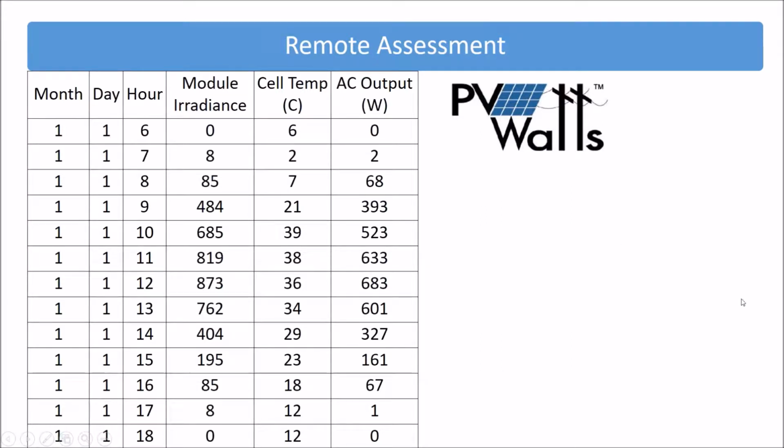And what you can see in this graph is, for every hour of the day, for every day of the year, what the power output of your solar array is. And so if you're asking what should be the parameters of my shade analysis so that I don't get any shade on the solar array? Well, here we're examining our production in the winter time, pretty close to winter solstice.